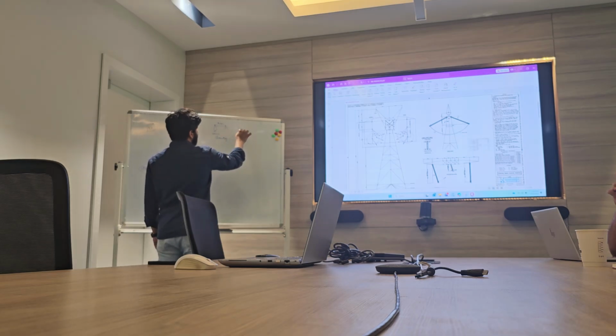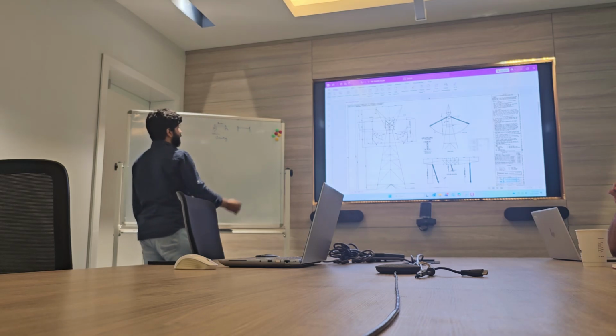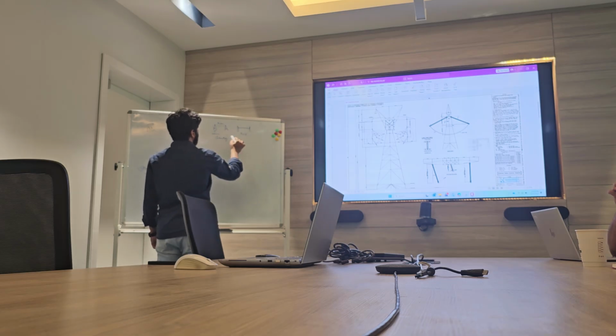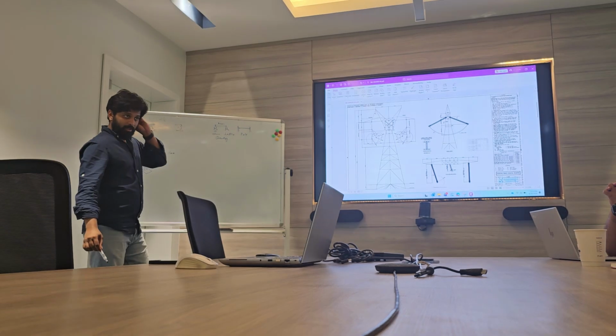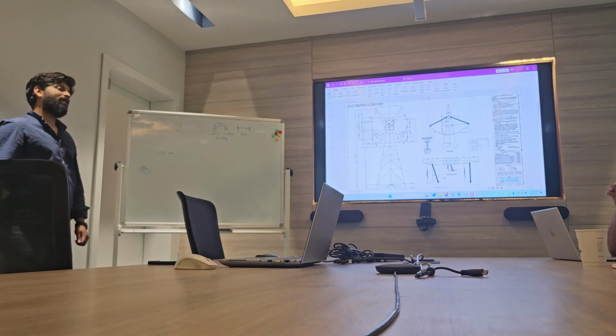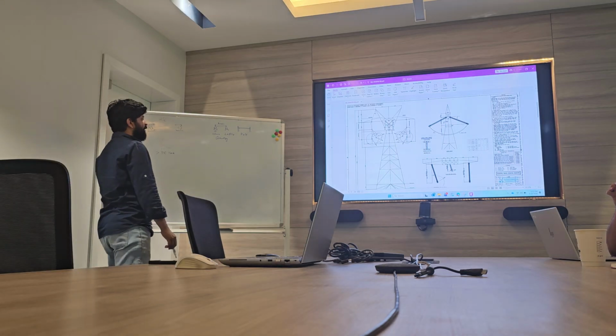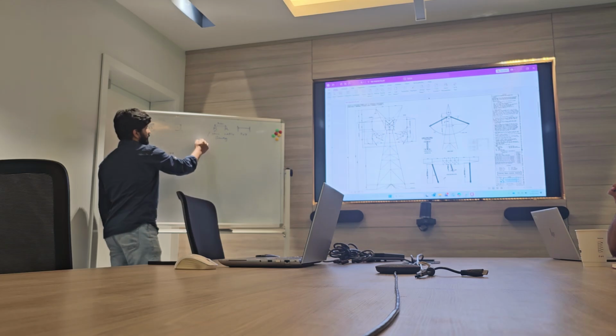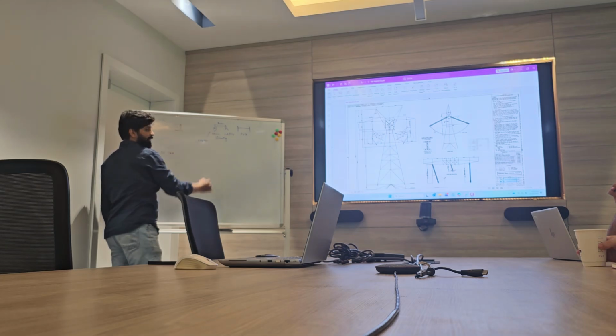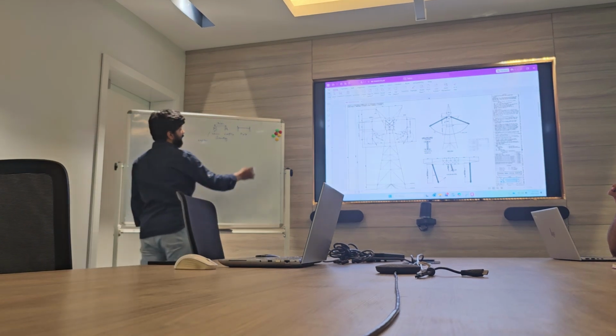A gantry can be of two types, either pole gantry or lattice gantry. Lattice means just a truss system, generally made by connecting different angles. It is lighter and more economic than pole.